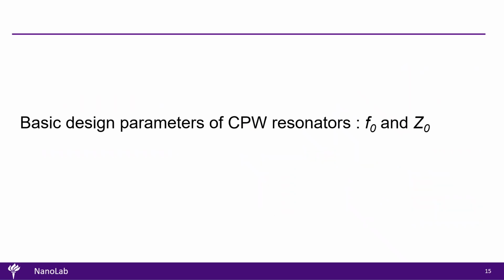When designing CPW resonators, two key parameters must be considered: the resonant frequency of the fundamental mode, F0, and the characteristic impedance, Z0, which determines how the resonator matches to external circuits. Both depend directly on the geometry and materials of the CPW.